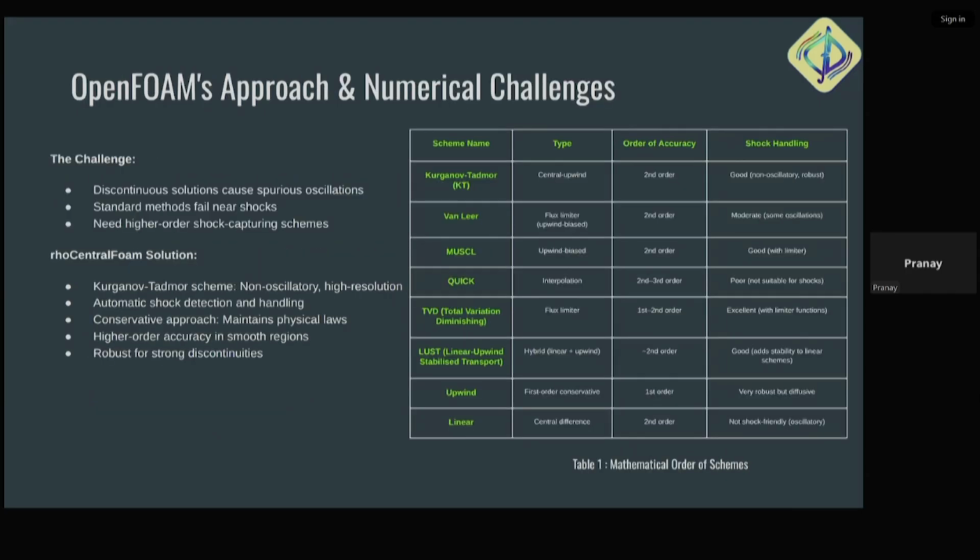So what are we exactly trying to do? I'll tell you more on this. As discussed earlier, we are trying to maintain a tandem with the previous lecture. So in the current simulation, I'm going to focus more on how to implement this using the rhoCentralFoam solver in OpenFOAM. What usually happens is, while setting up a case, it's easy to set up the boundary conditions, and it's relatively easy to get the mesh.